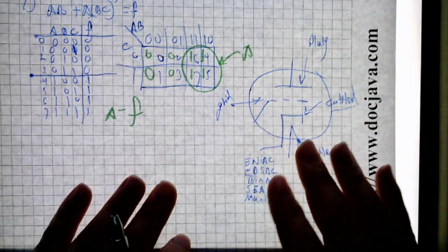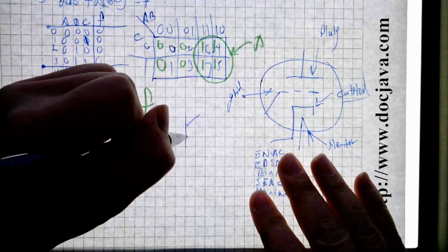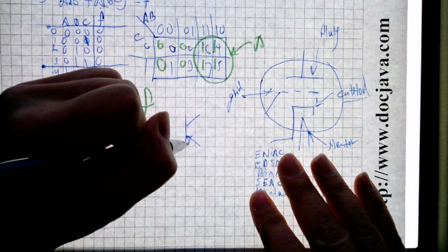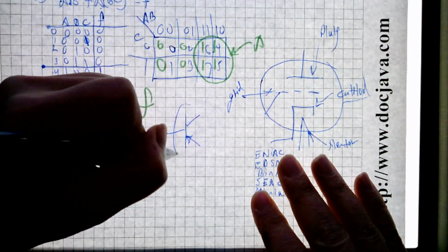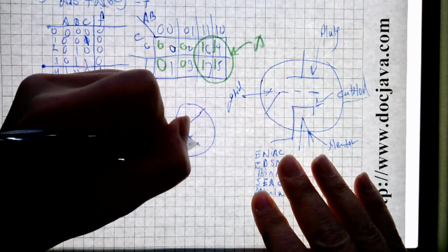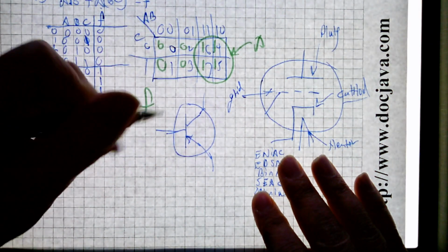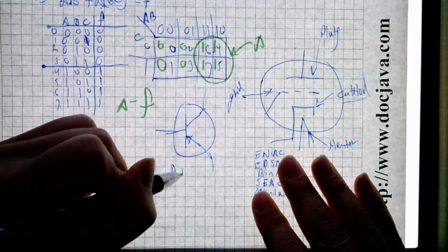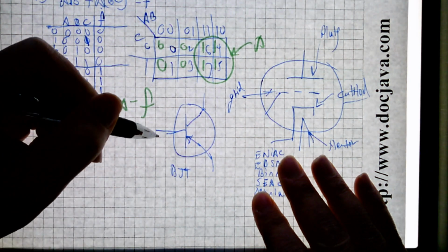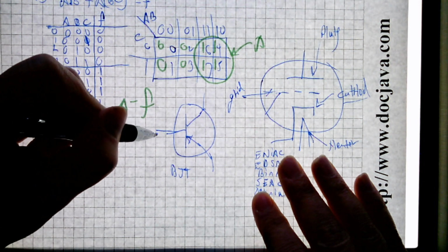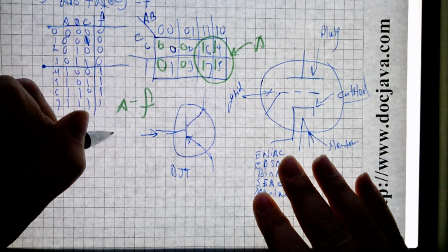And in fact, it's a common fallacy that people think that a transistor is just a switch. Just because they're in digital design class doesn't mean everything is either on or off. Even though I'm a computer engineer and everything must be either true or false or on and off. In fact, transistors, this is a current-controlled current source known as a bipolar junction transistor, BJT, is actually an amplifier, which we operate in saturation in order to make it a switch. But there is a linear mode.